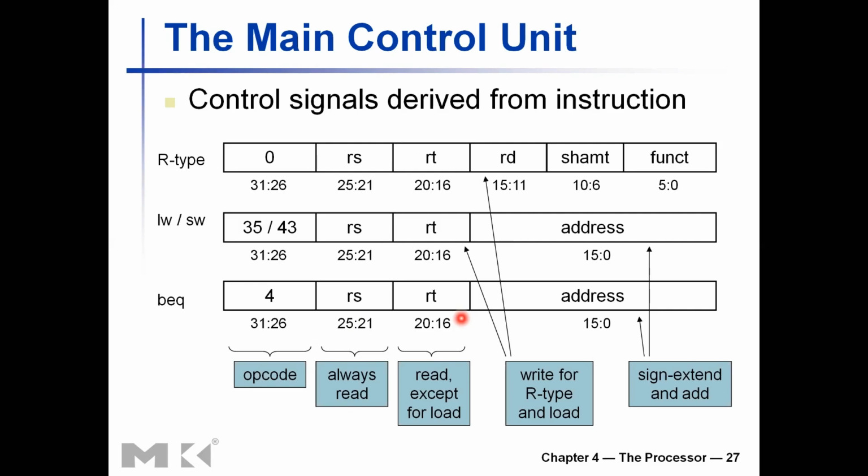So if you take the first 6 bits, always the opcode. If you take the next 6 bits, an operand, a register operand, other than jump instructions. So a lot of regular patterns here, which simplifies the control unit's hardware. So based on the opcode, you need to interpret these different bits according to the opcode and send them to the correct places. For example, register addresses to register file.